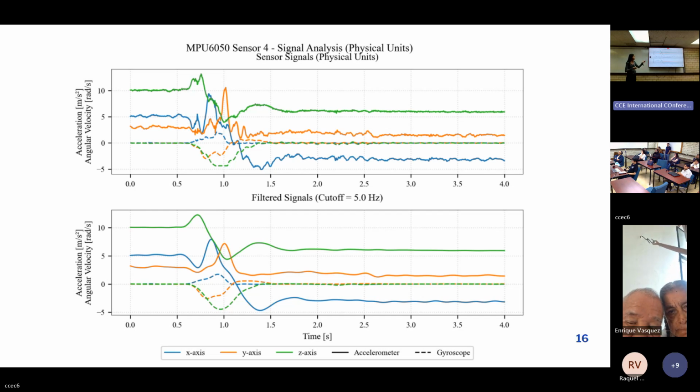And what we were left with was the overall shape of the graphs, which is what we really needed to be able to later recognize these gestures and differentiate them. We can also observe here that the time we had for each gesture was 4 seconds long. We did this on purpose, so each vector would be the same size. With the sampling frequency rate of 250 Hertz, we had a vector size of 1,000.